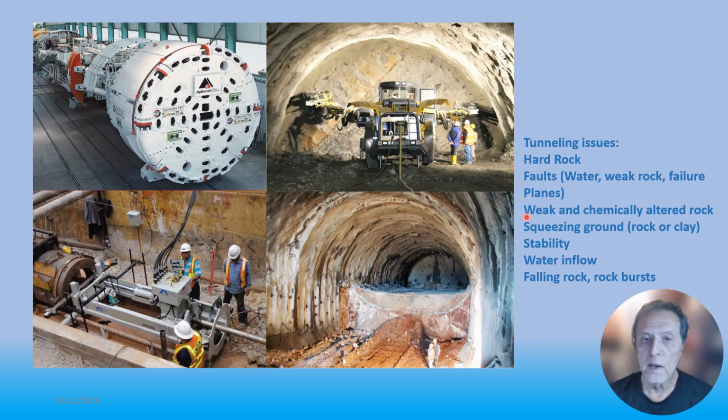Other issues include weak rock that can be quite dangerous. If it's too weak, it can burst out of the tunnel walls. Squeezing ground. If you have a clay, for example, that's a high swelling clay and you're tunneling through that, as you're tunneling through it, the walls of the tunnel can actually start squeezing inwards. General stability is something you need to look out for. Water inflow, of course, water seeping into, under, and through any structure is a crucial and potentially dangerous issue. You can have failing rock and rock bursts.